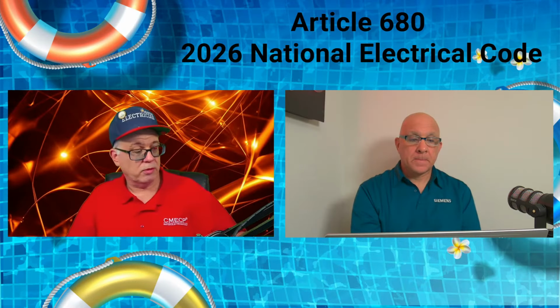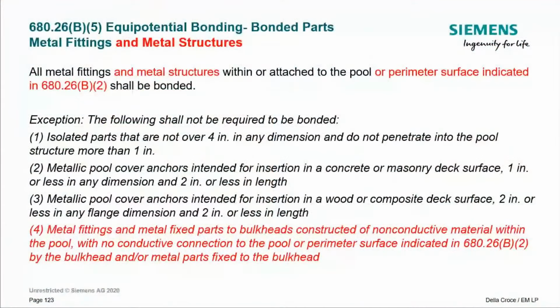Number two on this is metallic pool cover anchors intended for insertion in a concrete or masonry deck surface, as long as they are 1 inch or less in any dimension and 2 inches or less in length. Okay, so 1 inch in any dimension, but the overall length of the anchor that goes down into the decking is less than 2 inches, right?